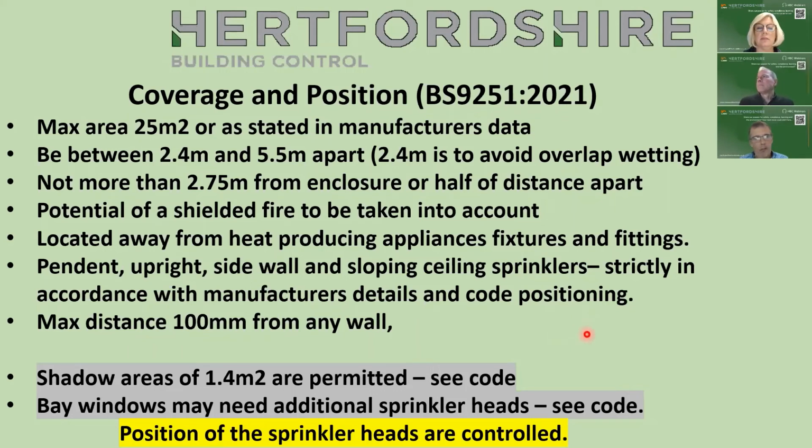to the edge of the enclosure. Potential of shielded fire to be taken into account. Located away from heat producing appliances, common sense kind of stuff. Pendant, upright, sidewall and sloping sprinklers strictly in accordance with the manufacturer's details and code positioning.